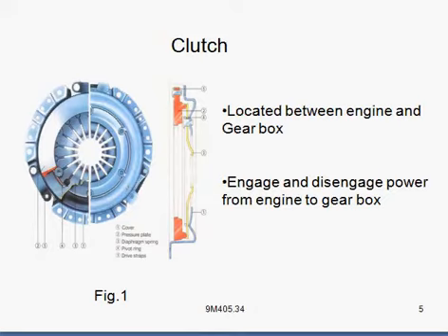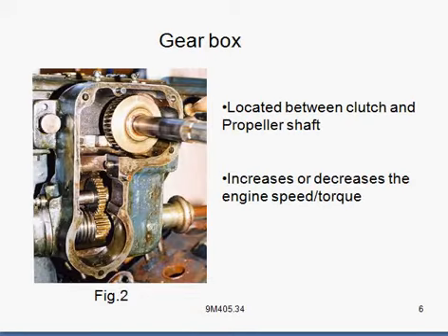Otherwise, there may be jerks or sudden loads, which will cause damage to the load and discomfort to the passengers also. In order to avoid this, the clutch is used, and at the same time it is also used for smooth engagement of gears.